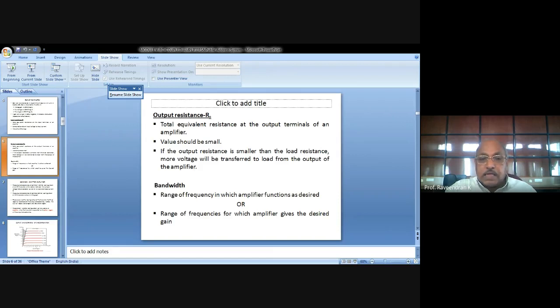Or in other words, the forward biasing of the base emitter junction is ensured by the proper selection of the resistances R1 and R2 as the resistance voltage divider network, or generally the voltage divider. So this current which is flowing through R1 will be I1.